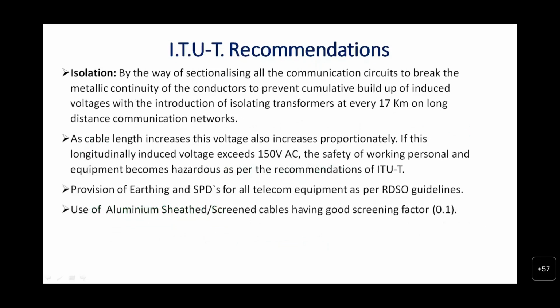Further, isolation by way of sectionalization of all the communication circuits is done to break the metallic continuity of the conductor, to prevent cumulative building up of the induced voltage, with the introduction of an isolation transformer at every 17 kilometers on long distance communication networks.